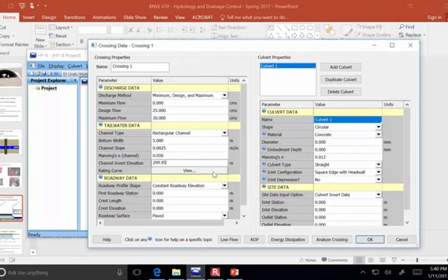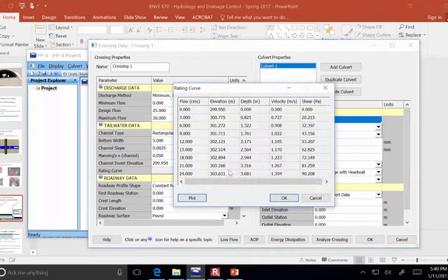299.95. We could click here and it would give us a rating curve that says what flow rate you get with which depth of flow. So in our 5 meter wide channel, if we have 4.4 meters of depth, that corresponds to the 30 cubic meters per second. That's the maximum we expect to see.